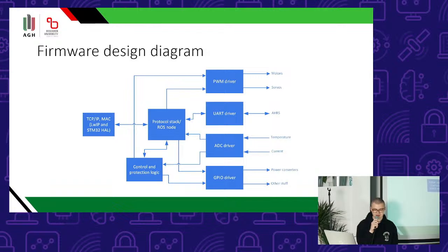What ROS does is provide a way of uniform inter-process communication. So in ROS there is some core process that handles the communication, and we have separate processes for all modules that are called ROS nodes. So here is an example of such a node, and the nodes communicate using a thing known as ROS topics. So the node can subscribe to a ROS topic and then receive the data associated with the given ROS topic.